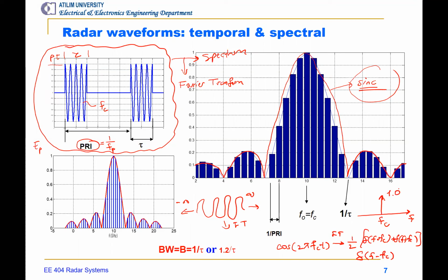However, when we want to take Fourier transformation of a cosine, you have to limit your cosine. It cannot be infinite to the left and right. You have to stop somewhere because you have a limited capacity of calculator. You have a memory, you have to put the data there, but you have limited size. Then you have to use limited number of samples over your cosine, and then you take its Fourier transformation.